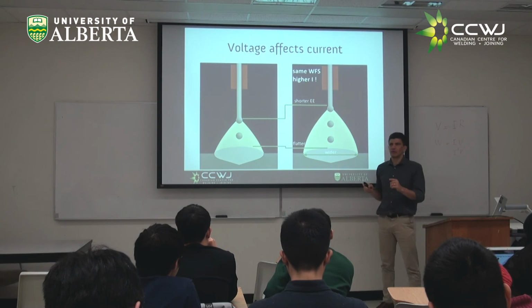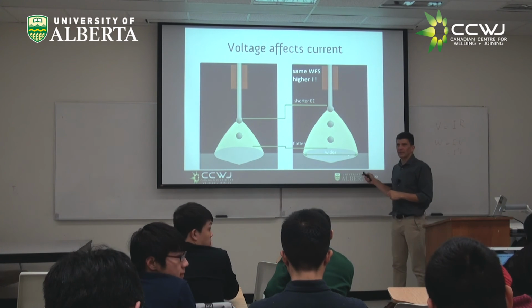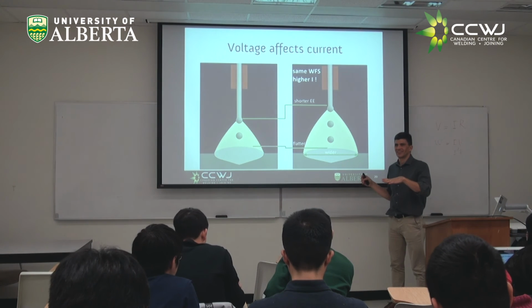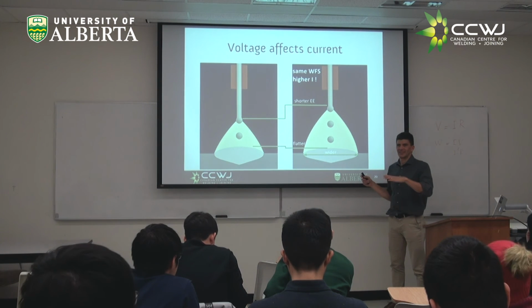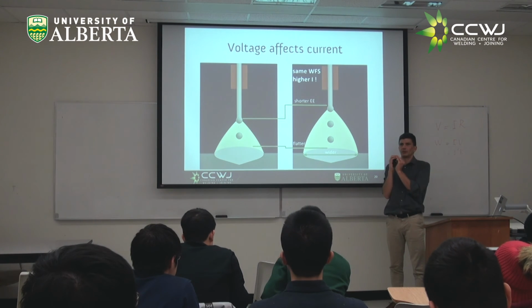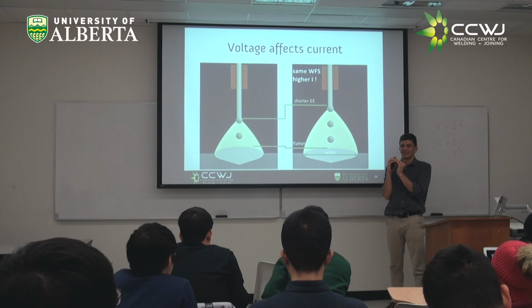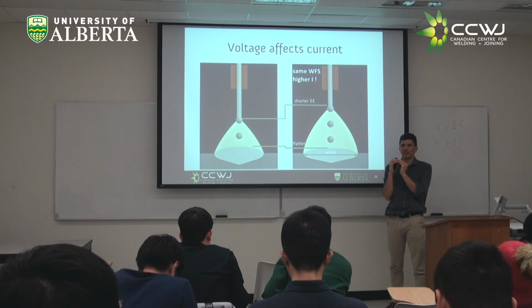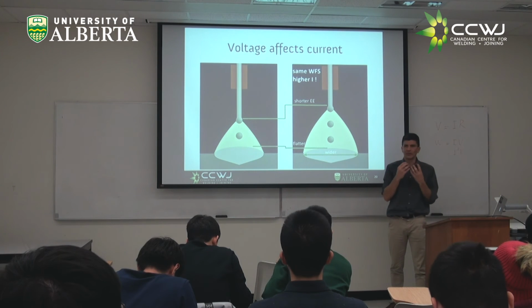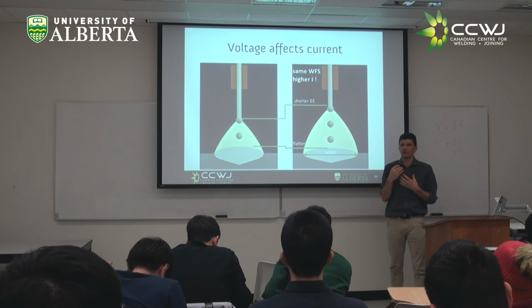I'm melting the same amount of wire, but this is wider, right? So it's going to be flatter. This is super important for things like fatigue performance. Typically, you want a flatter bead more than a crowned bead. Very often people say, oh, we have a crowned bead, blah, blah, blah. You start to get a sense of how the variables play.